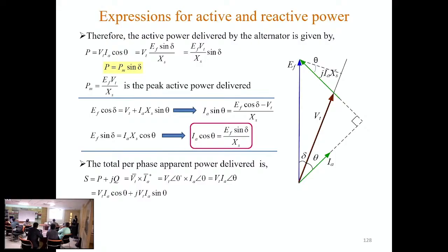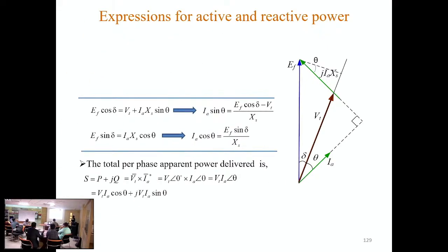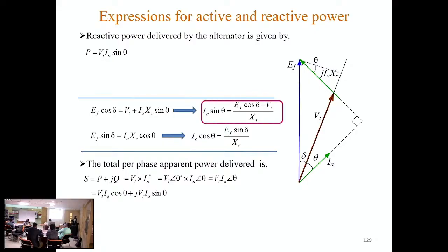So that is the peak active power delivered. Okay? And also we can find the expression for reactive power. So reactive power is Vt Ia sin theta. We have this expression Ia sin theta equal to this. So put this in that equation.